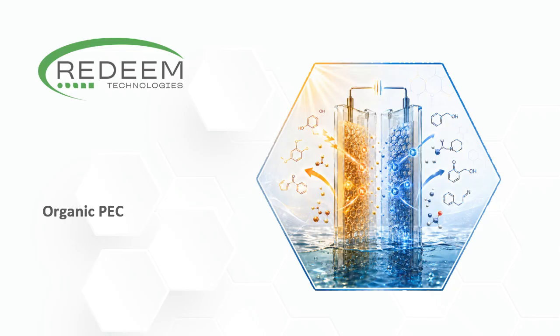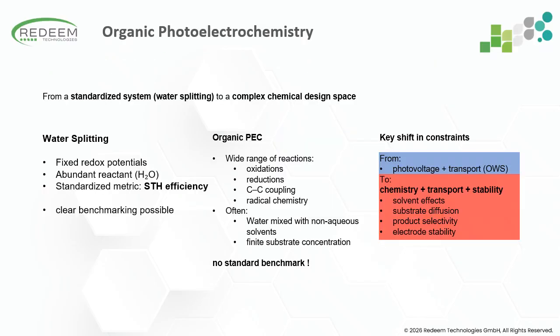And in the next section, we will look at how new requirements influence the reactor design and where the field currently stands. Before even discussing reactor designs for organic PEC, it's important to recognize that the engineering challenge fundamentally changes compared with water splitting. Water splitting is a highly standardized reaction, so we always work with the same reactant, fixed redox potential, and universally accepted performance metrics, making benchmarking between different systems relatively straightforward. Organic PEC is fundamentally different.